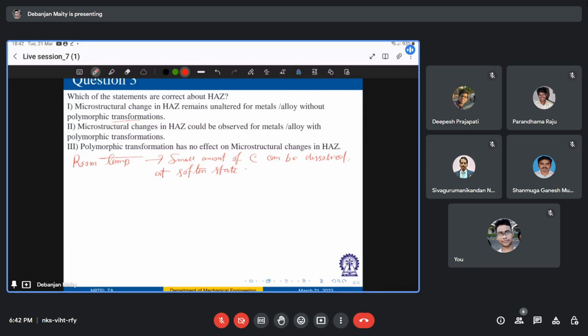And what will happen above some upper critical temperature? I hope the upper critical temperature is somewhere around 900 degrees C. Above the upper critical temperature, alpha ferrite undergoes a phase transition from BCC to FCC structure. It's called gamma austenite, right? Austenite is also relatively soft, but can dissolve considerably more carbon, as much as about 2% carbon at around 1100 degrees C. I don't exactly remember, anyhow.